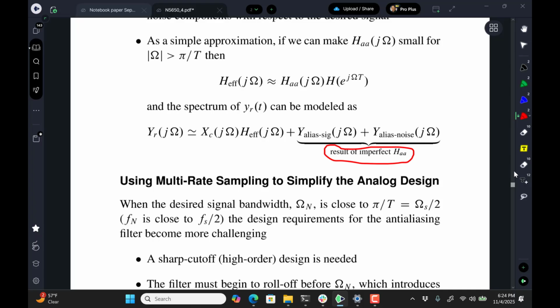So building this higher order filter that can drop all of the spectral energy from our input signal, the harmonics and things that can only get in and cause aliasing and then fold back down into our spectrum and sort of disappoint us in a big way. And maybe I need to stop there and think about it.